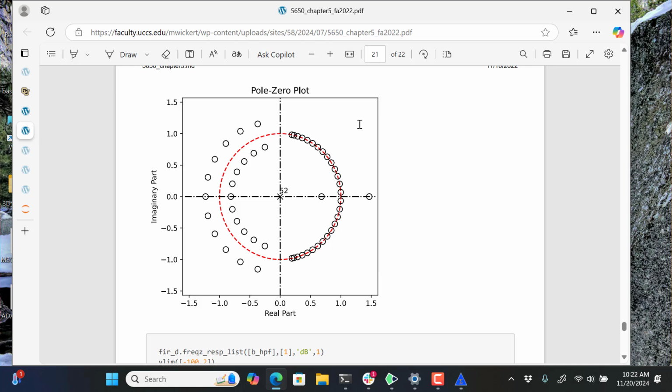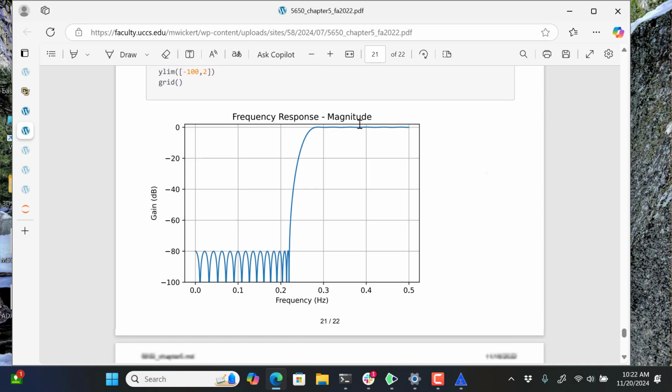Now, do you know it's a high-pass filter or not? Just guessing at it from the pole zero geometry we went through. What do you think? These are all on the unit circle, so those would all be tack down points, right? In terms of what we were looking at from geometry. If you swept around on the unit circle for your frequency response, you'd be getting hammered down to 0 over and over again. These quadruplets here are defining your passband, is what it turns out. And I have the picture of that, I'm pretty sure I put in here. Yeah, there it is, right there.